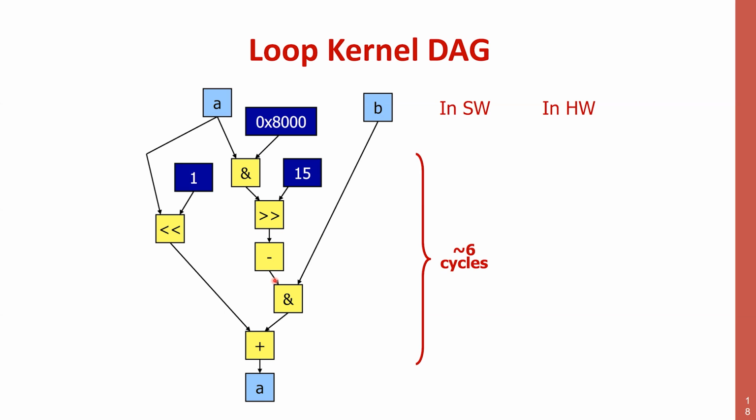And -1 in 2's complement, which I suppose is the representation here, because it was a program in C, so it assumes 2's complement, has ones in all positions of my word, 32 times 1. So now let's think. I have here 0 that enters, all the bits are 0. I have 1 that enters, all the bits are 1. So I don't need any transistor to do that, right? I need to connect this bit here, which is the same thing as saying the bit 15 that was here, and connect it to all the 32 bits of this bus, of this signal.